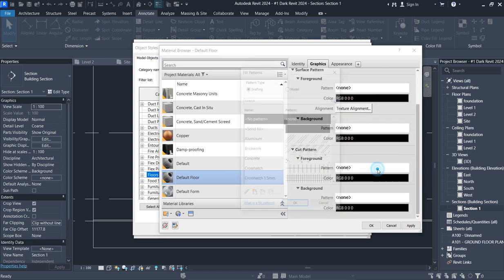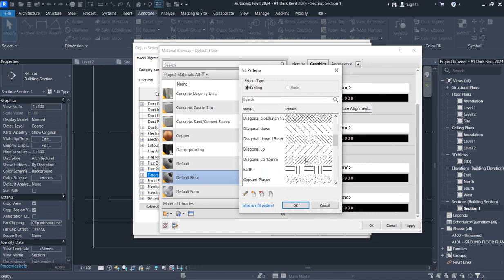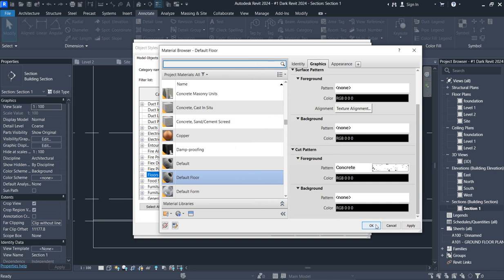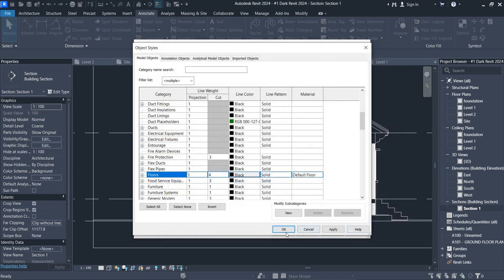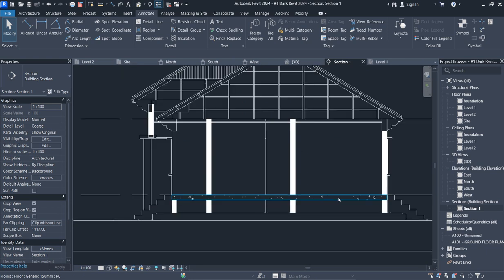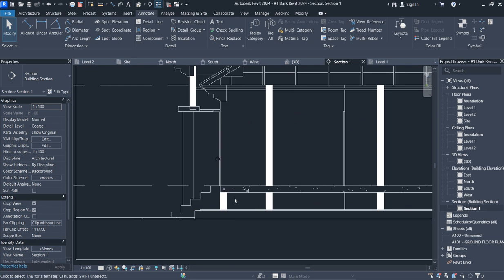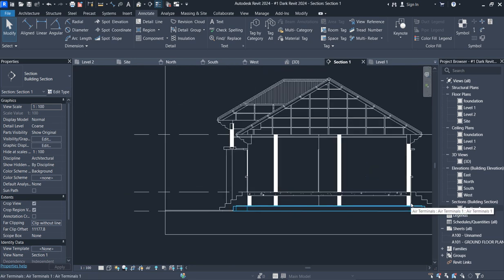So you cut pattern. This is what you want to use in cutting references. So this cut pattern, what I need to do is concrete. So I'm going to click on concrete and create whatsoever I want to create in that level. So this one does not have modeling, just only pure drafting here. So click on that and click on this. Say OK, and then click OK and click OK. So can you see? This pattern comes up, and the detail aspect of it is here, alive, and every other thing. So if you have this one in place, this is good for you.